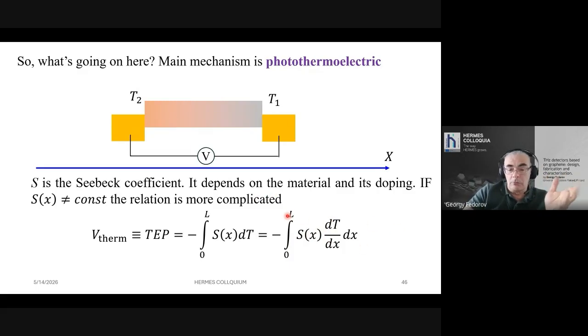That's important to know. And in order to convince you that this thing actually does work, I want you to recall that there is an object called a thermocouple, which we use to measure relatively high temperatures in furnaces and other things like that. When you have two metals outside, this is the same metal, and a different metal inside, and you have different temperatures of these contact areas, you will have a thermoelectric power that is proportional to the difference in temperatures.